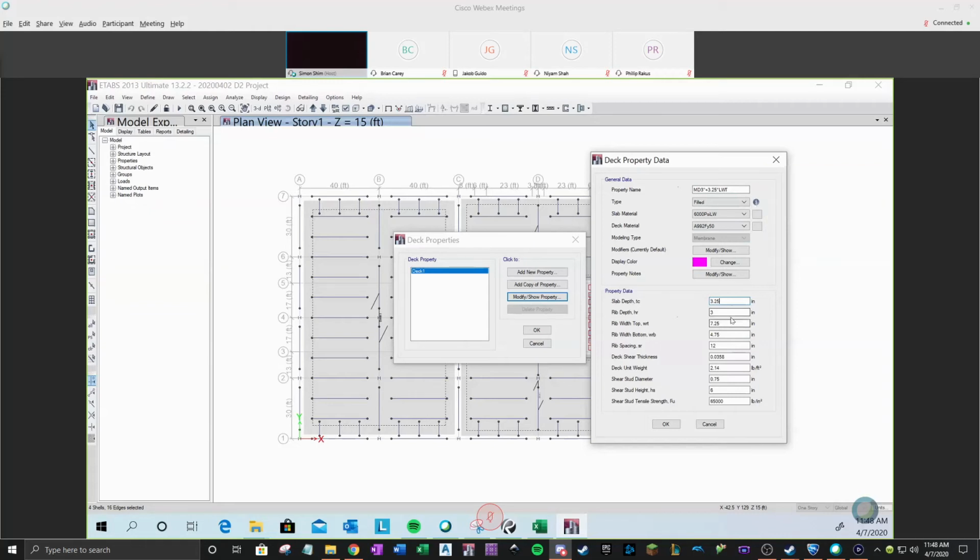I think you maybe can adjust it as needed, but generally, rib depth of the metal deck and concrete thickness are the most important for that configuration. And here, the slab material is somehow f'c 6000, but for metal deck concrete we especially don't need a high strength concrete. Our industry commonly uses 3500 versus 4000 psi concrete.